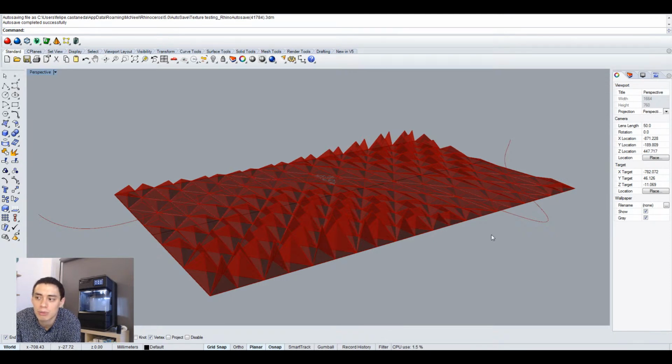But the point here is that I'm able to make really fast changes because I'm not committing to the geometry just yet. When you make those changes after you've created a fairly complex model in SolidWorks, it's very possible, especially with the amount of data you're managing here, because each individual panel is now a new surface, that your program might crash. And if you're talking about a larger assembly or a more complex part, it gets really tricky to model these types of surfaces. But it's possible. Fusion 360, SolidWorks, Rhino here, they all can do it. My preference is just Rhino.